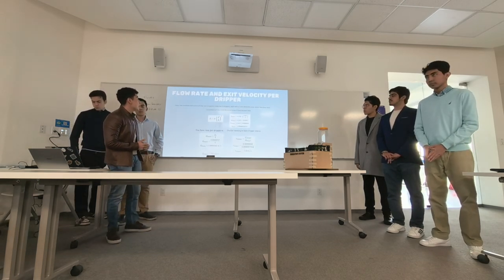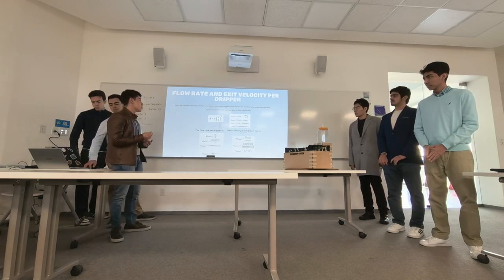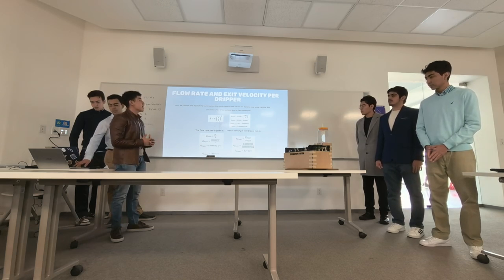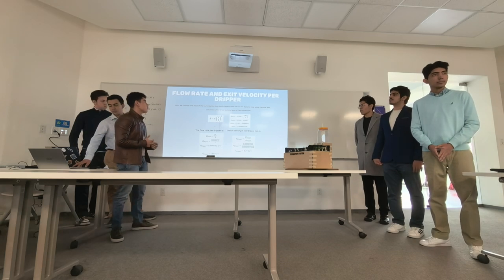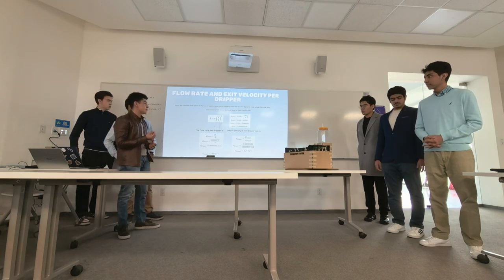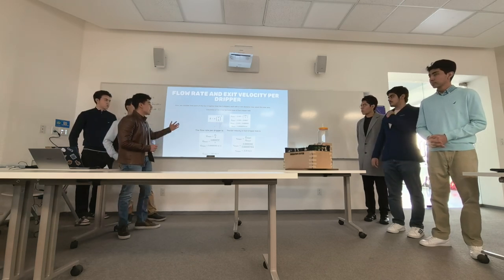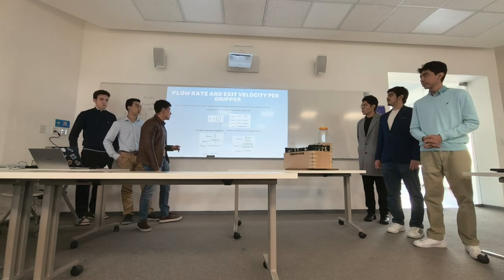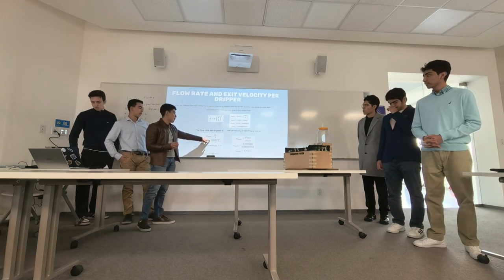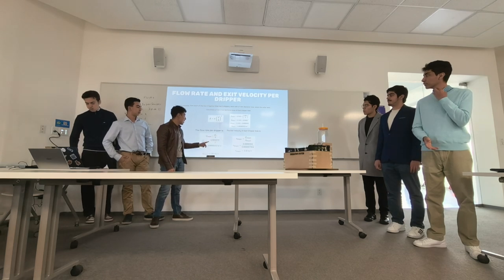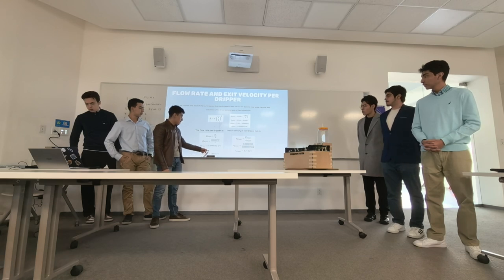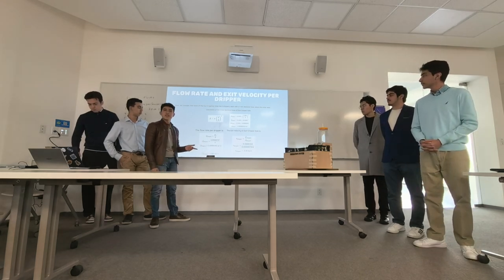Okay. And now we're going to talk about the drippers, which are the holes where the water exits. There are 3 drippers in each line, and each one has a 1 millimeter diameter hole where the water exits. So we can now calculate the area again, because this time it is different, because the hole is smaller. We use this area in the calculation of the flow rate, and we divide it by 3. The flow per dripper is 2.62 milliliters per second.